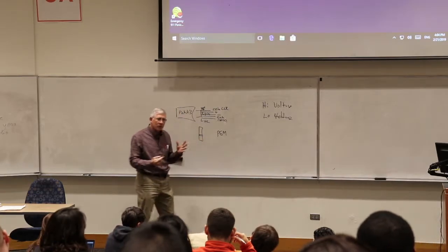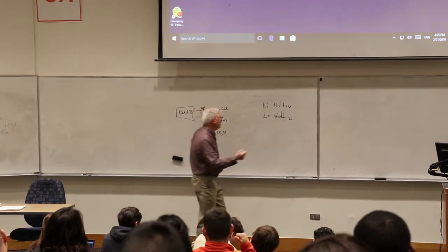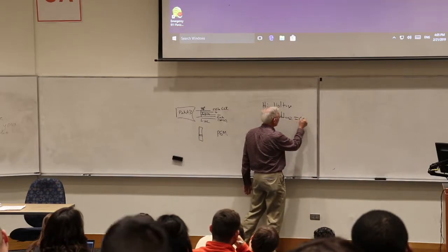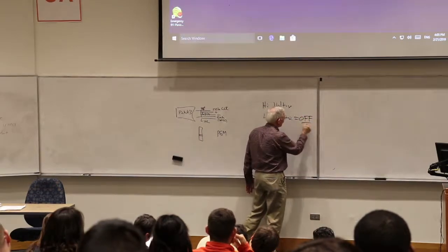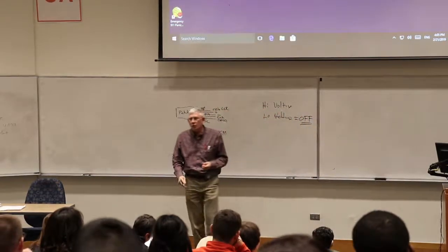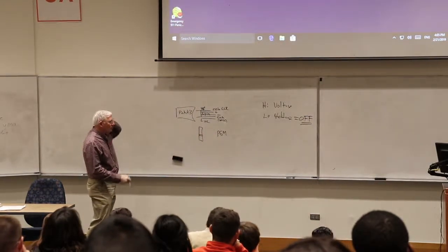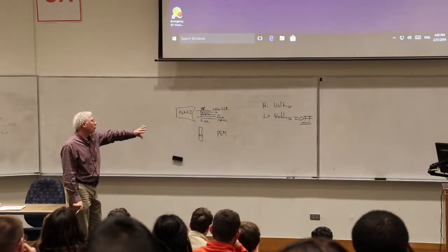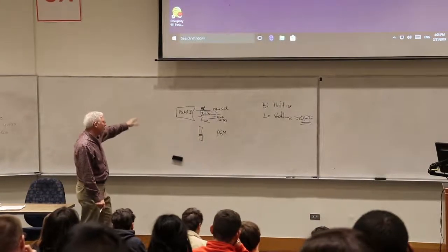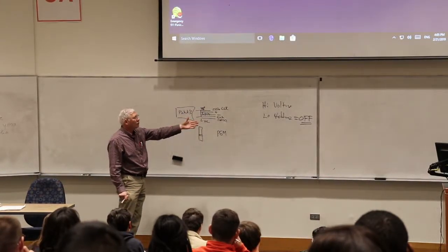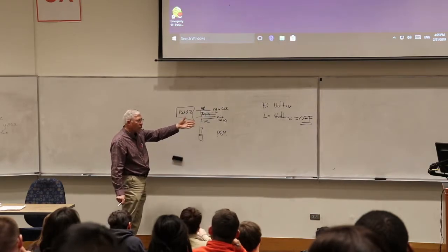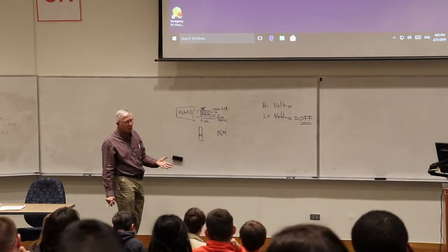For that reason, the advice was to set low voltage programming to off unless you were really going to use it. I saw that someplace, and it's just been in the back of my mind. So without giving it much thought, I always used the PICkit 3, and we set the configuration bit in the configuration words for low voltage programming off.